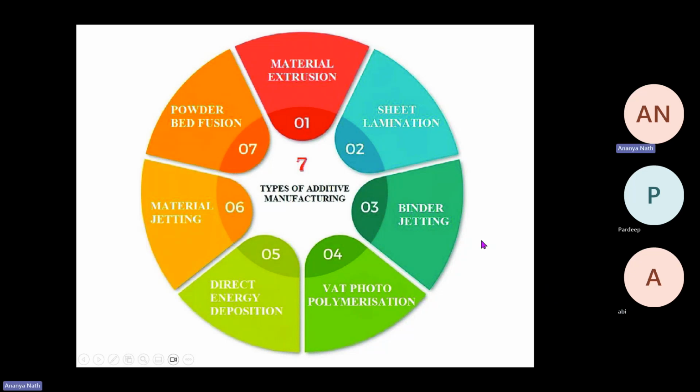Okay. So this energy source can directly interact with the raw material, and you can get the final shape and geometry. So the support structure is needed to dissipate the heat that is being generated because of this energy source and to provide the mechanical support. But among all the processes, binder jetting is the only process where you actually do not need any support structures.